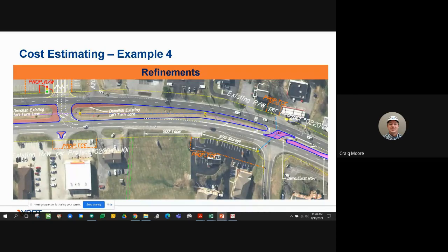Another component here is our storm drainage system. We understand that, but also making sure that, you know, where is this stormwater going? Do we have an adequate easement for that, and how are we accounting for those things? Part of that gets into the proposed temporary construction easement along this area, where we may potentially need to bring the storm drainage system through.